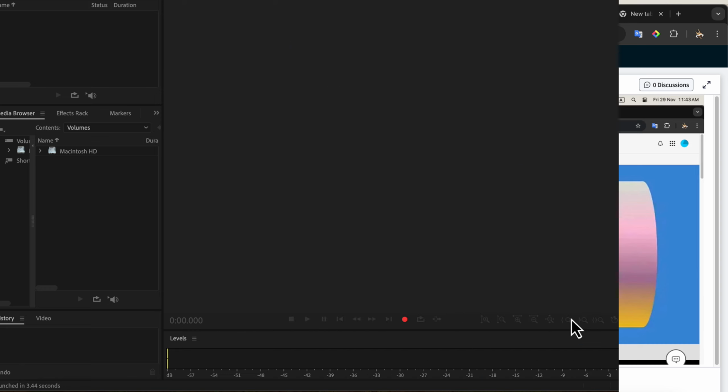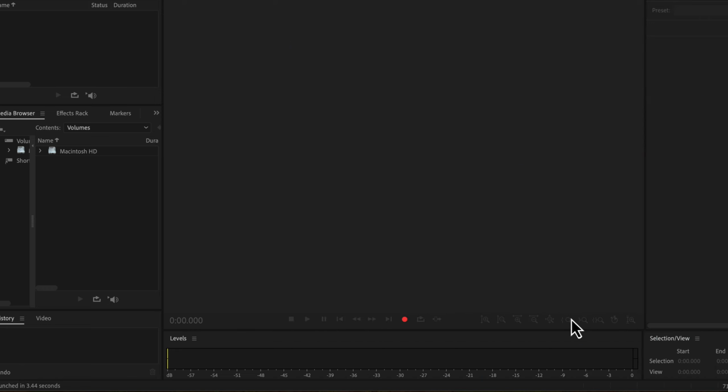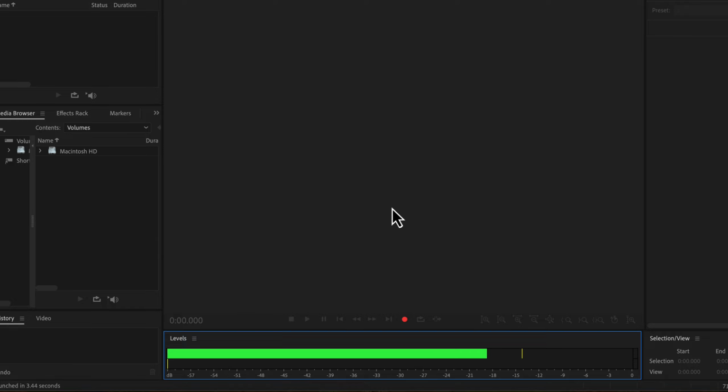Let's get back to our learning of Adobe Audition meters. Notice all the numbers in this meter are negative, and the highest value is 0. The louder the audio is, the closer it will be to 0. Double-clicking inside the meter area will show its current level. Of course, you will see this level while you record, but you can check it before recording to make sure everything is okay.